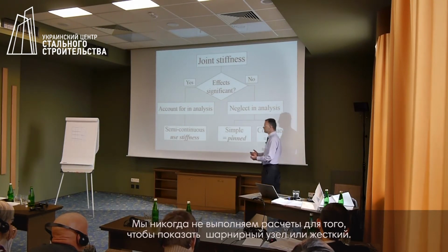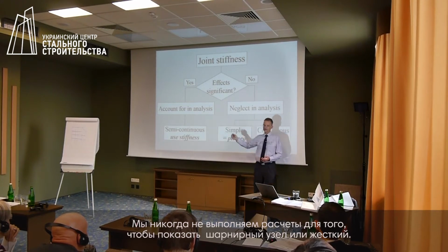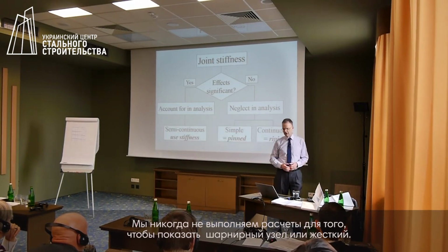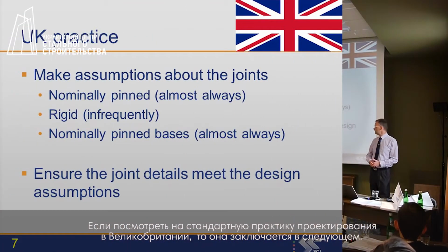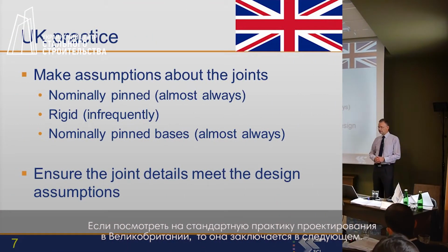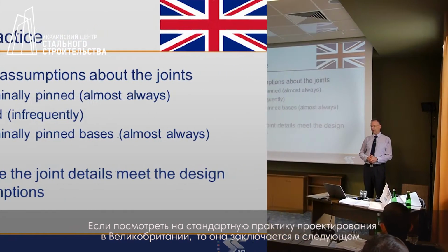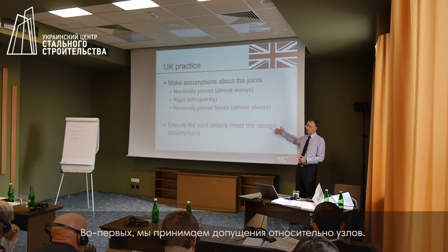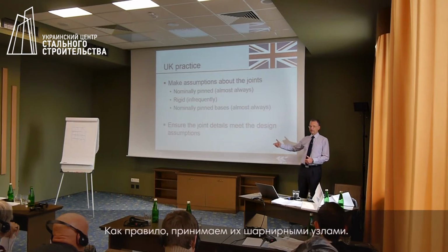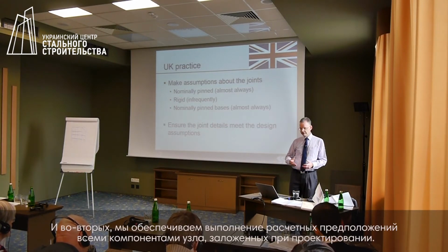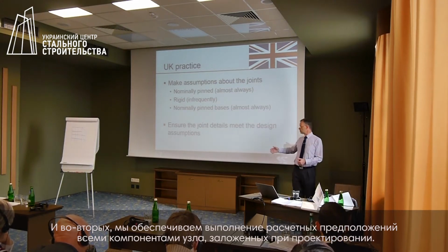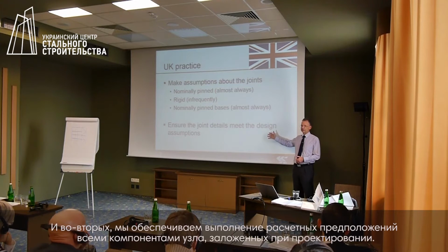We have never ever done any calculations to demonstrate that they are pinned or continuous. So the process in the UK is generally to assume that connections are pinned and then make sure that when they are detailed, they achieve the assumptions made in design. Or alternatively, to assume that they are rigid and then make sure that the joint behaves as a rigid joint.